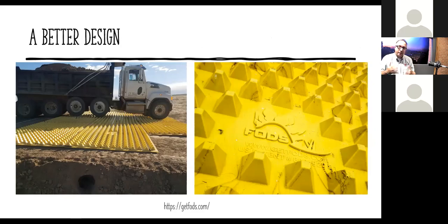And that's one of the things we've noticed is that track-out control points for many projects tend to move, especially roadway projects. They tend to change places, or even subdivisions. So this makes it so that, yeah, you might have a higher investment up front, but chances are good you're going to be able to reuse these over and over and over again. And you still will design it similar to TC1 so that they're draining into the site.